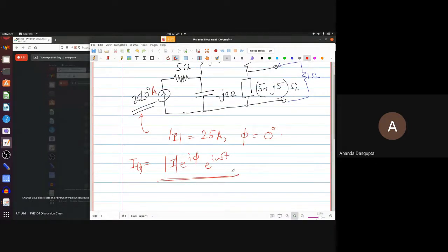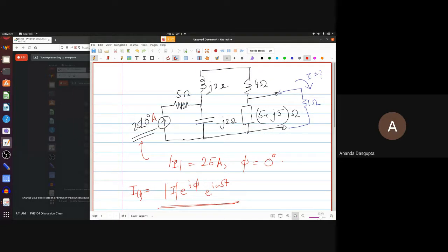In all these problems, unless otherwise mentioned, you're going to assume that a sinusoidal input has been given. That's obvious because you are specifying the impedances of these inductors and capacitors, and they have definite fixed impedances only for a given frequency. So we are assuming that some particular frequency has been used for which the impedances are 3 ohms, 2 ohms, etc.